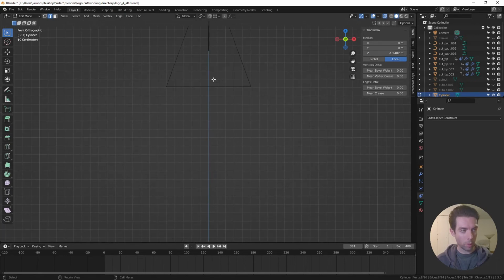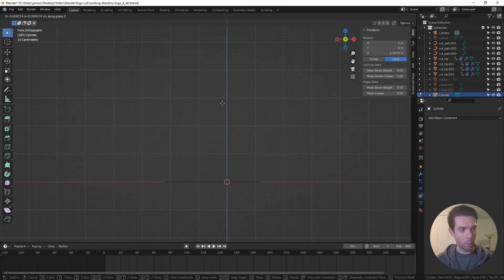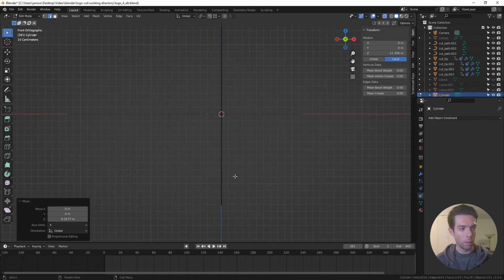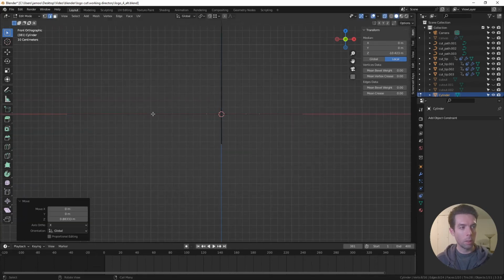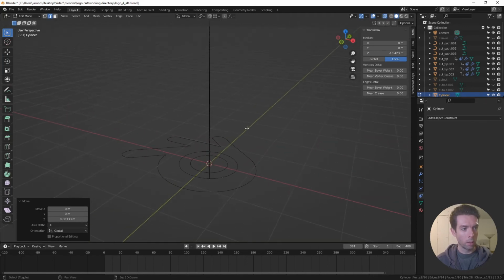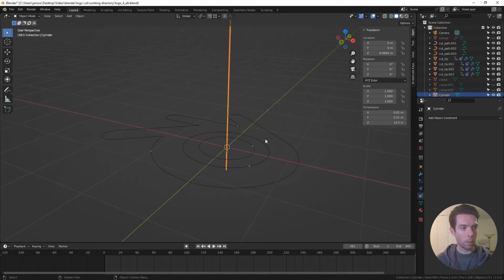And then we can take those, and I just want to move them down along the Z-axis. And just make sure they're a little bit below the origin down here. So I'll tab back out of that. I can do Alt-Z to undo the X-ray mode.